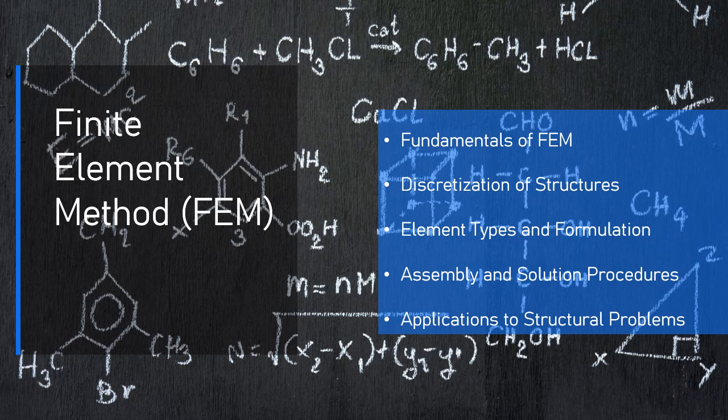The global matrix K and the global force vector F are modified to account for these boundary conditions by eliminating rows and columns of K and adjusting F accordingly. 4.2. Solution of the system of equations. Once the global stiffness matrix K and global force vector F are assembled, the primary goal is to solve for the unknown displacements, U, of the system.